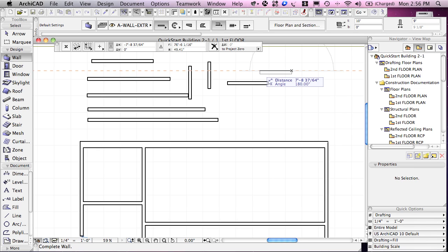So in general, I prefer using the tracker, and I recommend that you use that in preference to the coordinate palette. You don't usually have to put in a letter like X or Y, or A for angle is only necessary when you're going off of one of the guidelines, and R, or radius, is actually identical to the distance as long as you're in relative mode, which is activated by this little checkbox or this little icon there. Now the R value will be the distance based on that point. So this is called the delta triangle, and this tells it to measure relative to the last click point.